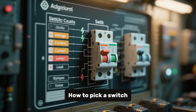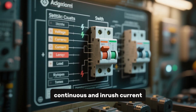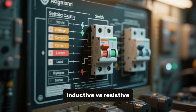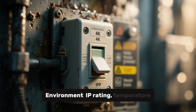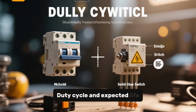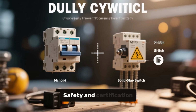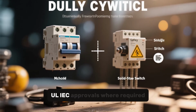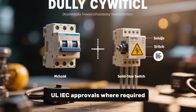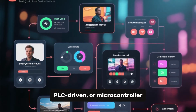How to pick a switch. Define the load: voltage, continuous and inrush current, inductive versus resistive. Consider the environment: IP rating, temperature, vibration, corrosives. Consider duty cycle and expected life, and choose mechanical or solid state accordingly. Safety and certification, UL/IEC approvals where required. Control interface: manual, PLC-driven, or microcontroller.